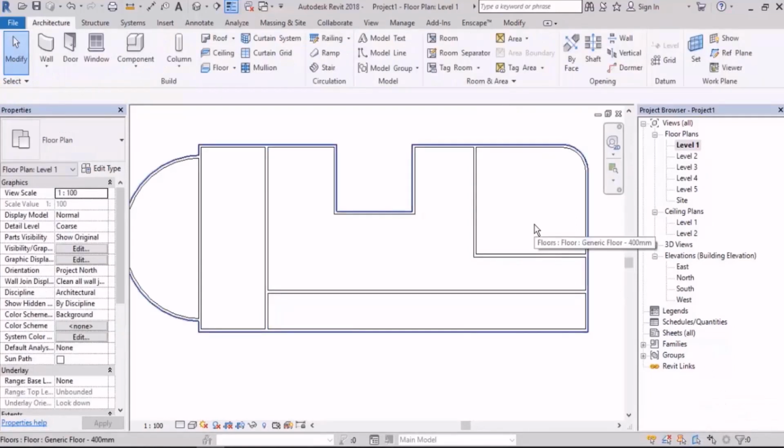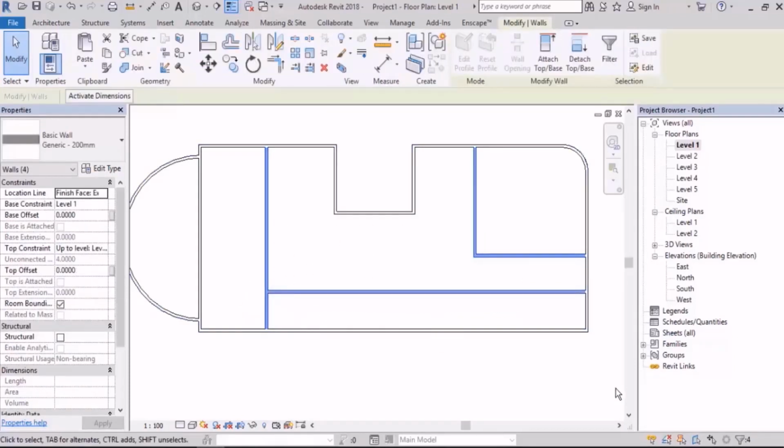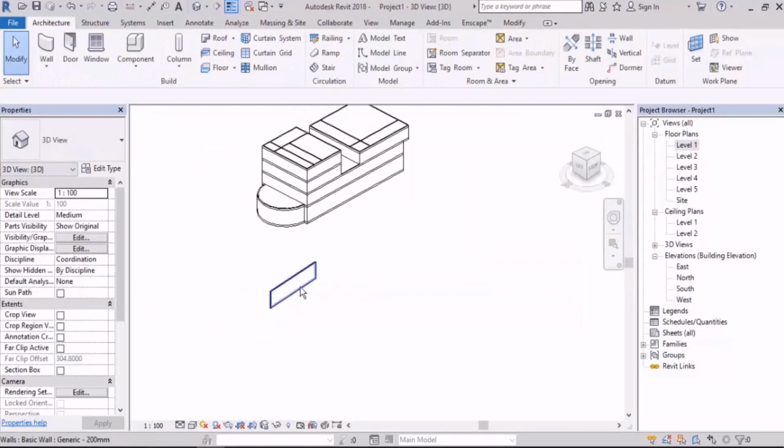There's also a trick, if you want, you can use it. If your select elements by face is on and you want to open a box, at the point that you want to start it, hold the shift, and when you want to drag it, leave it. Let's say it again, so I can understand. At the point that you want to start the box, hold the shift and start opening the box. Now I'm still holding the shift, and yet I haven't finished opening the box, so I leave the shift and then continue the box. It kind of turns off the select elements by face temporarily.